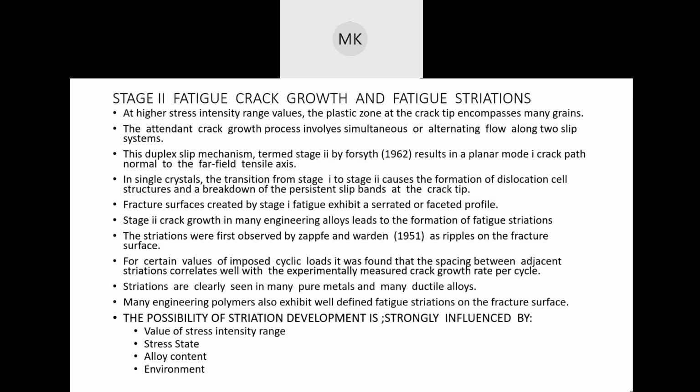Striations are just like how I have told this in class before. It's like looking at a tree and looking at the circles in a tree for its life. The amount of striation tells you whether the material is really ductile or had a lot of plastic deformation before failure, and all those things can be seen by looking at striations.